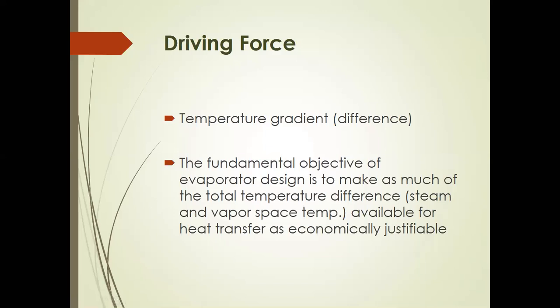and that is focusing on the main reason why the evaporator is able to concentrate the solution or the feed, and that is the temperature gradient, which is the driving force. Now, this temperature gradient or driving force is the difference between the temperature of the steam and the temperature of the feed inside the evaporator. In some problems, it is referred to as the vapor space temperature.